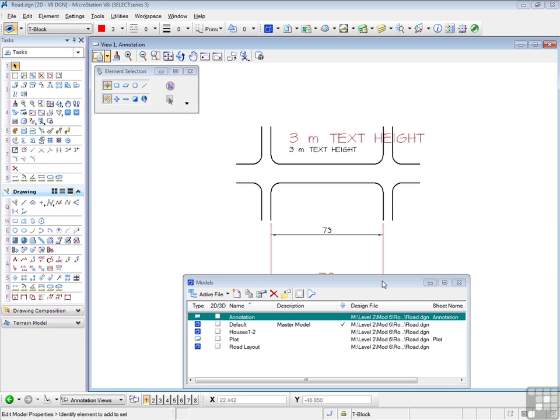And let me give you a different alternative to placing text in this manner. You could have originally placed text in dimensions at a 3mm height in this drawing, which is the expected printed text height. If you did this, you would need to apply a 1:1000 annotation scale for the originally anticipated print scale, which is available in that drop-down list. Or to print it in the 1:2000 scale, you would have to make a custom scale in the drop-down list.